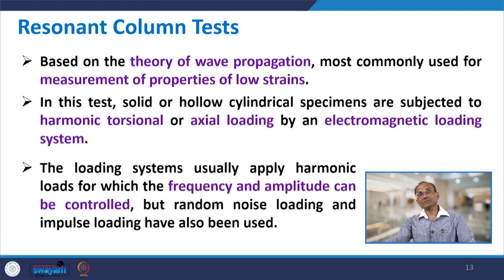In this test, a solid or hollow cylindrical specimen is subjected to harmonic torsional or axial loading by an electromagnetic loading system. We are going to discuss it in detail. You have a cylindrical specimen, similar to what is used in the triaxial test, and it is hollow and subjected to torsion loading like this, or it may be subjected to axial loading, which is longitudinal loading.